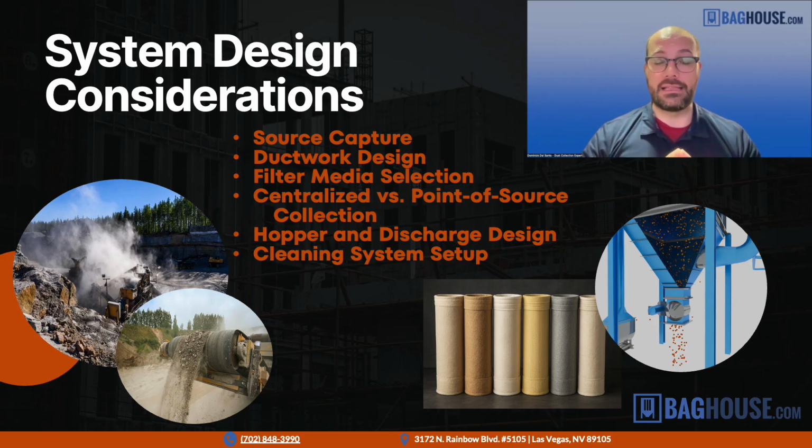Ductwork in general is the thing that takes the most amount of engineering and time when we're designing a system. People think it's the baghouse or the dust collector, but often I'd say 80% of our time and efforts go into designing the ductwork. And a lot of the problems that happen in older cement and mining plants are because the ductwork over the years gets changed, modified, neglected. And each time it's changed a little bit or repairs are done in a less than ideal way, it's the death by 1,000 cuts. And that's how you end up with a lot of the problems at these facilities, because the ductwork is not ideal, not so much the baghouse.